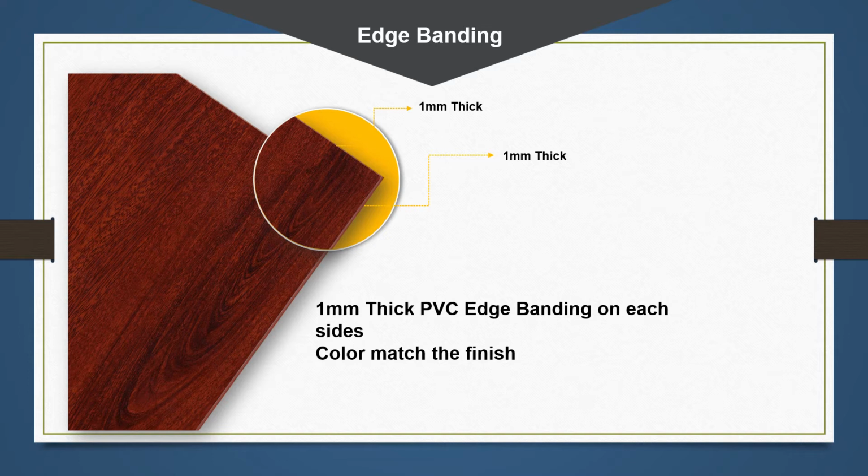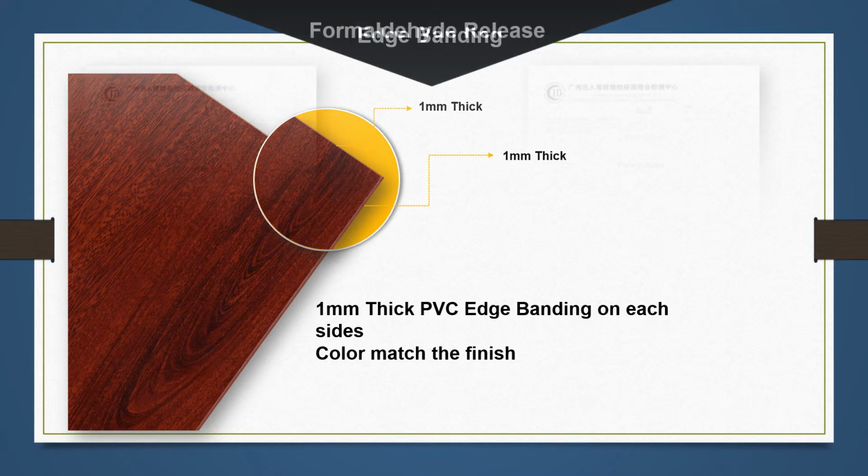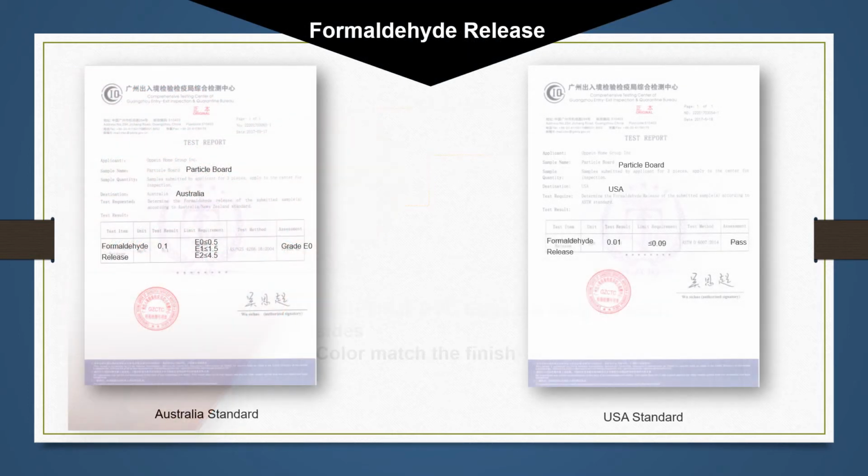For different colors and grain of door finish, we use different PVC with similar color and grain to match it. This is also a really practical process, since it's really likely that we need to do some adjustments on site, sometimes due to an uneven wall, sometimes due to inaccurate measuring, sometimes due to shipping damage, and we need to make a new door panel on site with the additional panels. We cut it into the right dimensions we want and use edge bands to cover the exposed edges. With actual edge bands and a big additional panel, we can avoid lots of after-sales troubles. We recommend always providing some actual parts like this. This can help solve most of the potential issues.